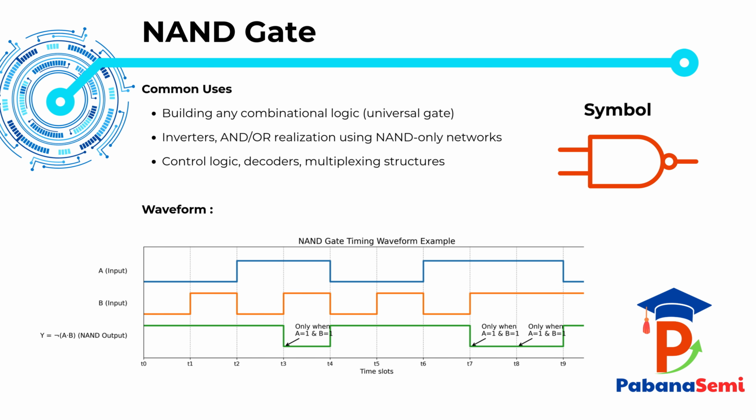So the waveform clearly reinforces the NAND rule. If either input is 0, then the output is 1. Only when both inputs are 1, the output becomes 0.